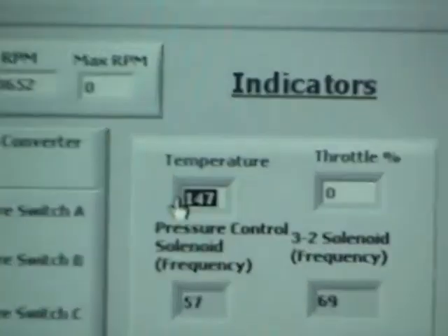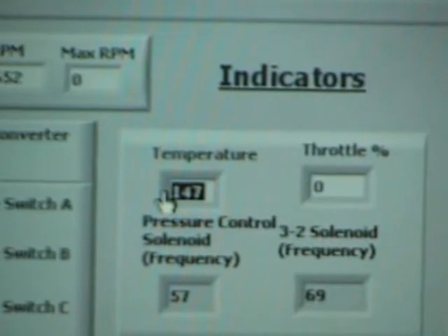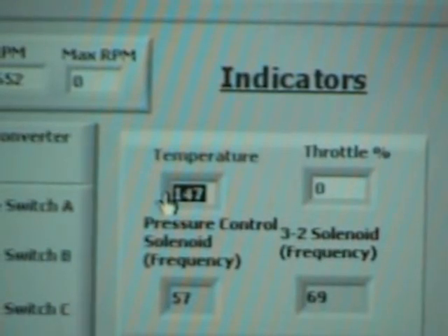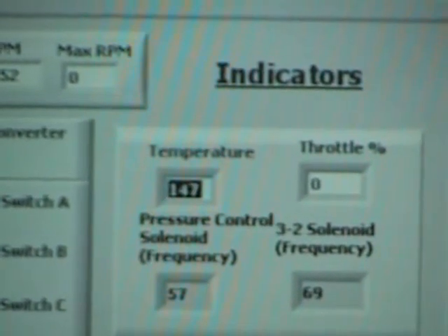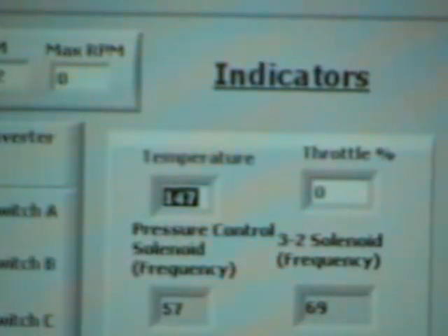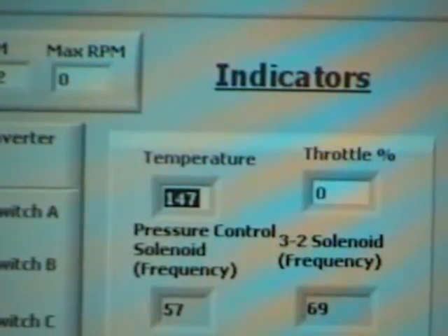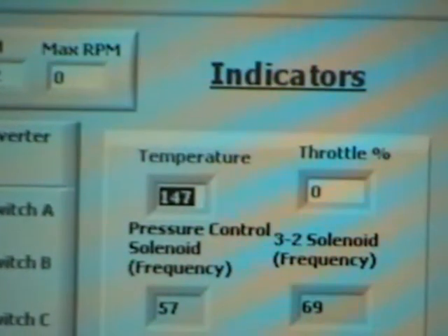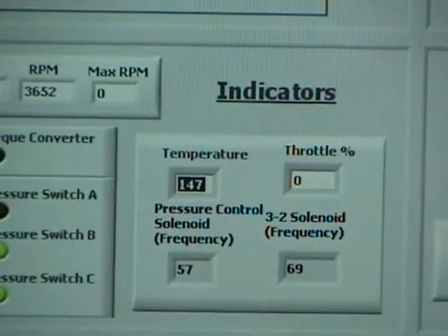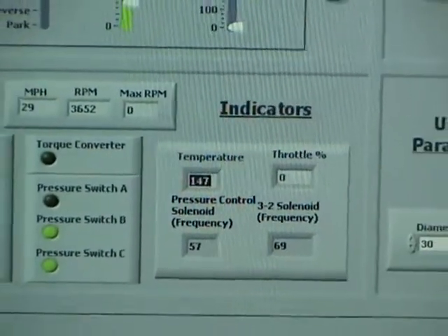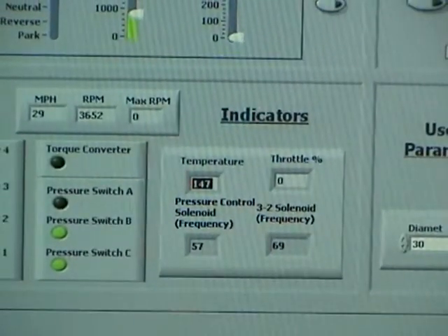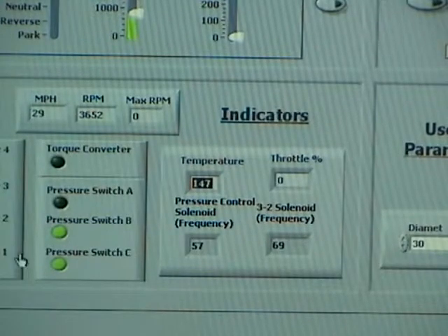Also, it notifies if the engine is overheating, and if so, it would downshift the vehicle into gear 3. No matter if it's supposed to be in 4th or not, it's going to downshift it to 3 and pulse the TCC on and off to indicate to the user that something is wrong with their vehicle, and then also to allow the transmission to cool down.